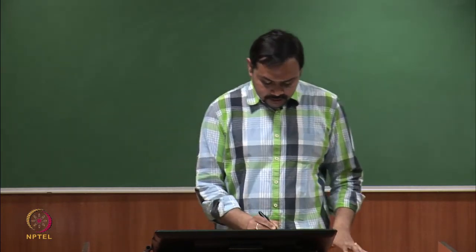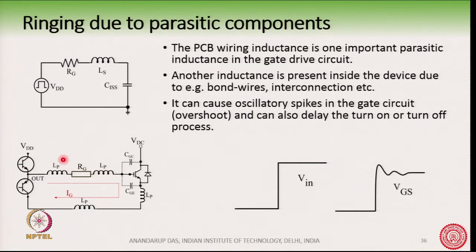So, we would definitely want to make this distance short. Here it is shown, this LP, these are part of the PCB wiring inductances. So, these should be minimized as much as possible.